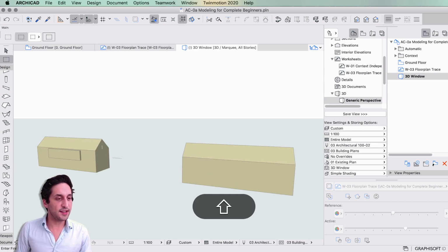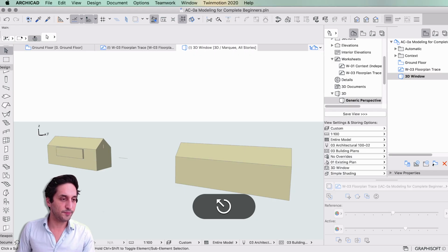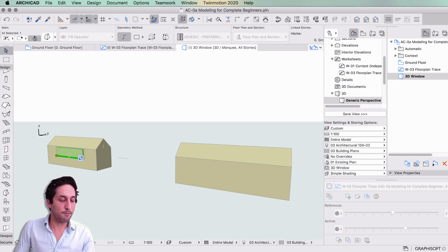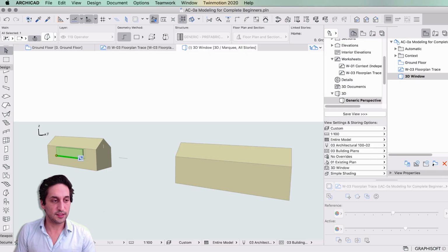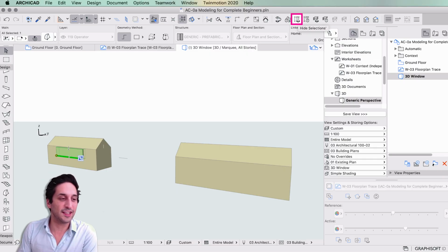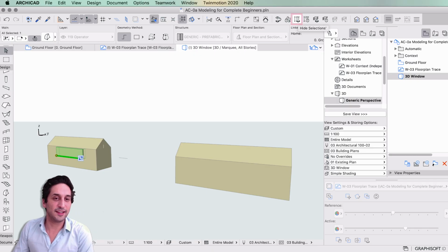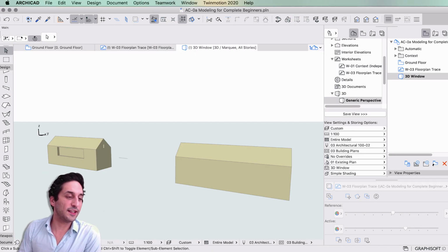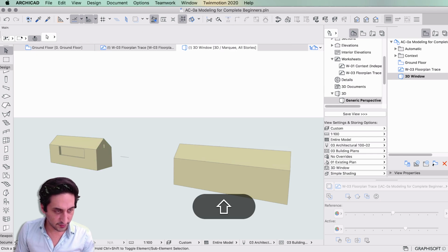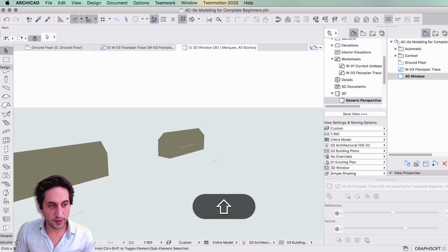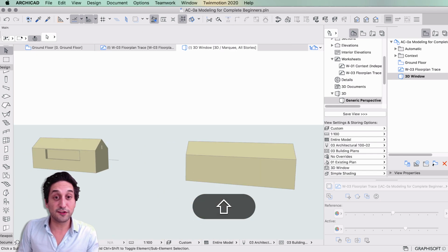So the left side is the example. As you can see here, we are actually modeling a solid that we are then going to use as an operator to generate the openings. And then we can turn this off, as I'm going to do now using this button here, hide selection. It hides the selections layer. So when that layer is off, then you see you have the actual surface that we can now 3D print with the openings. So let's go ahead and do that.